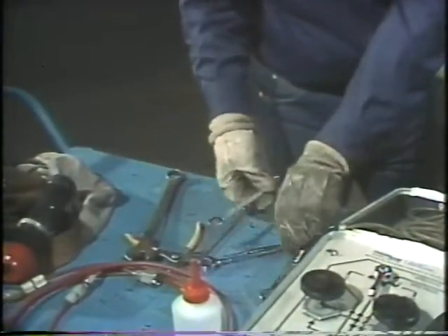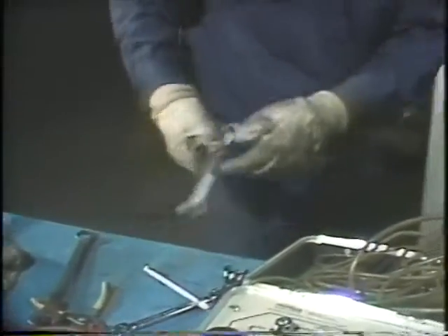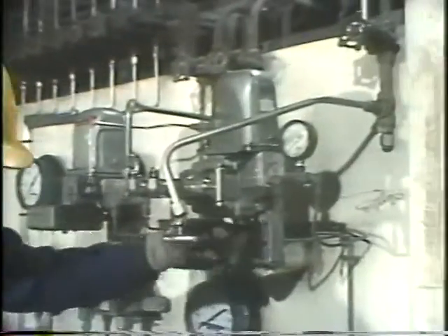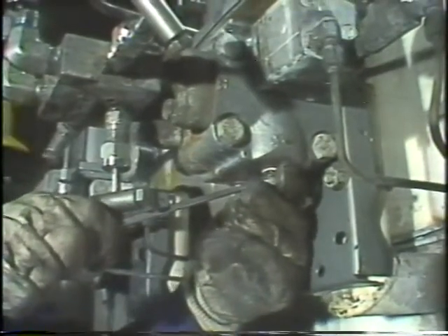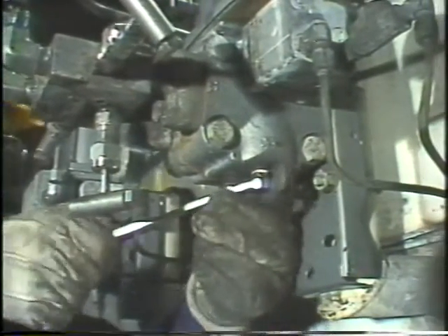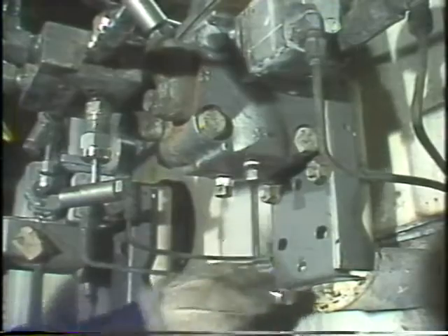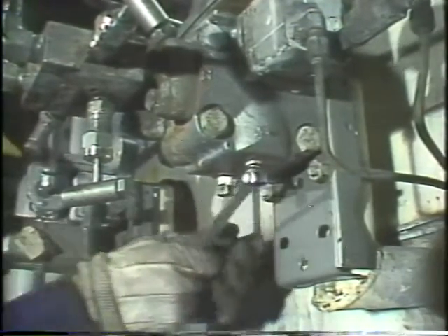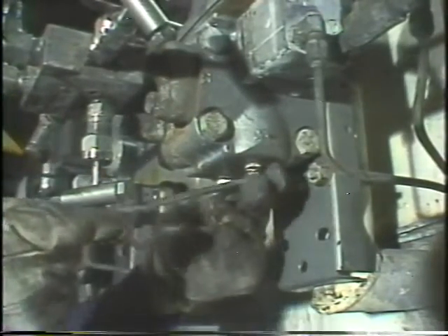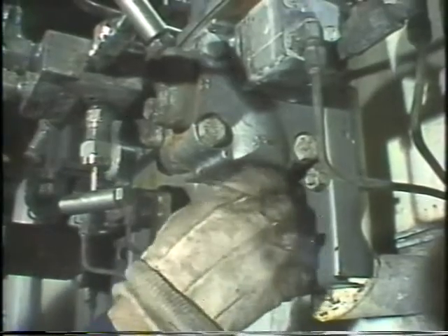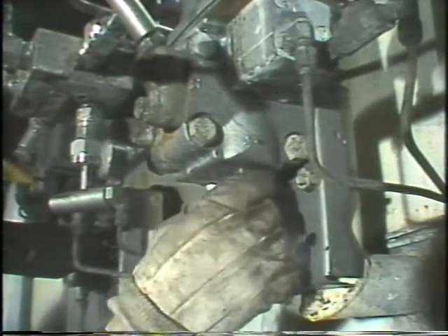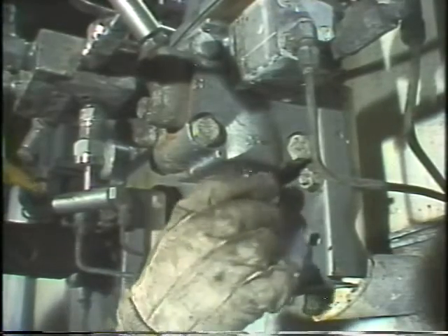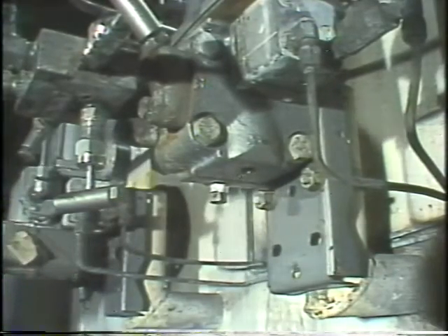Okay, now I'm going to have to drain the liquid out of the DP cell itself. It's got plugs here underneath. This is the high pressure side of the DP cell. Before I put this transmitter back in service, I'll have to remember to put some more Teflon tape back on the threads of these plugs. There, that's good.